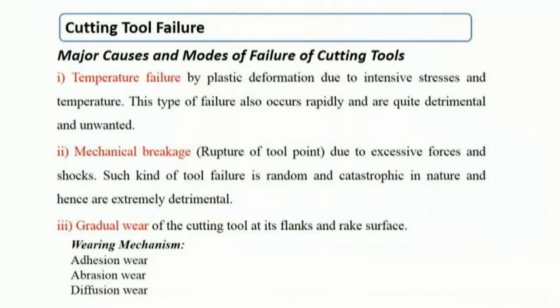The second wearing mechanism is the abrasion wear. So that is due to the detached particles from the chip that may abrade over the rake surface, or maybe by overflowing of those particles onto the machined surface may cause failure on the rake surface or on the flank surface.